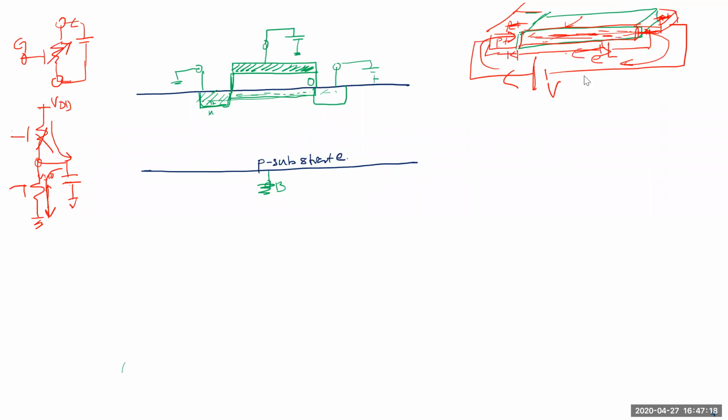If I want to make it through this circuit, then obviously there are electrons here and there are electrons in the battery. The battery electrons will flow here, the positive amount will go from that and recombine, and so on. The question is, will it flow through this? Well, if it is a P plus, like you said, it looks like a reverse bias diode because there are holes present, but they will recombine, and that will be a very small recombination. Whatever minority charges are there, only that much will recombine and you'll get a tiny amount of current, which is the reverse bias current.